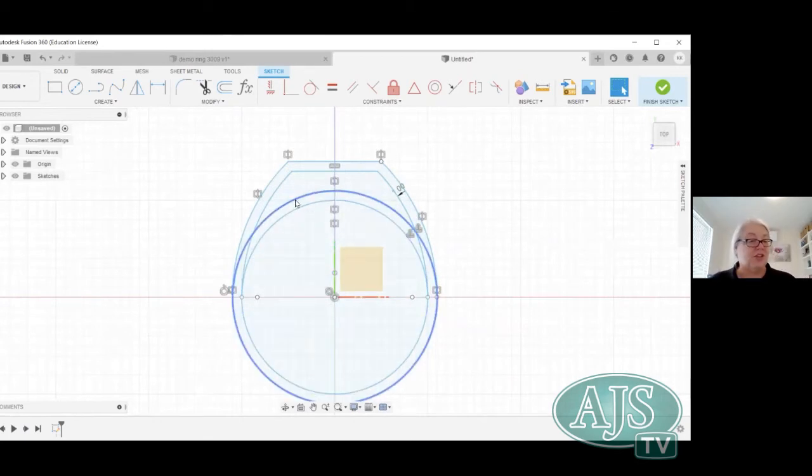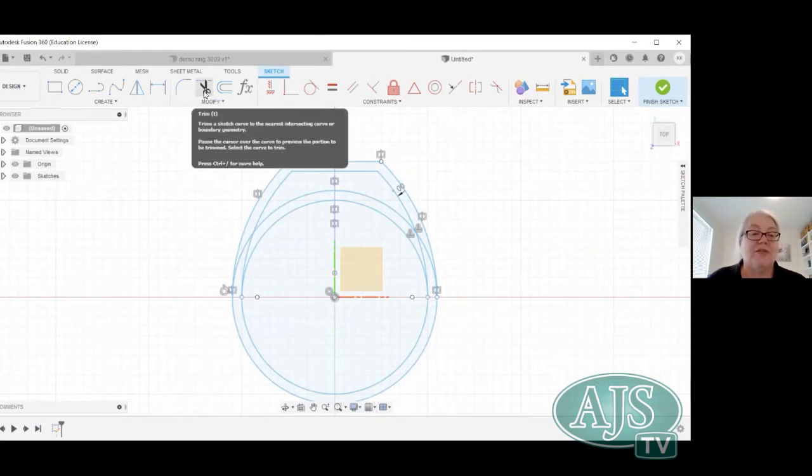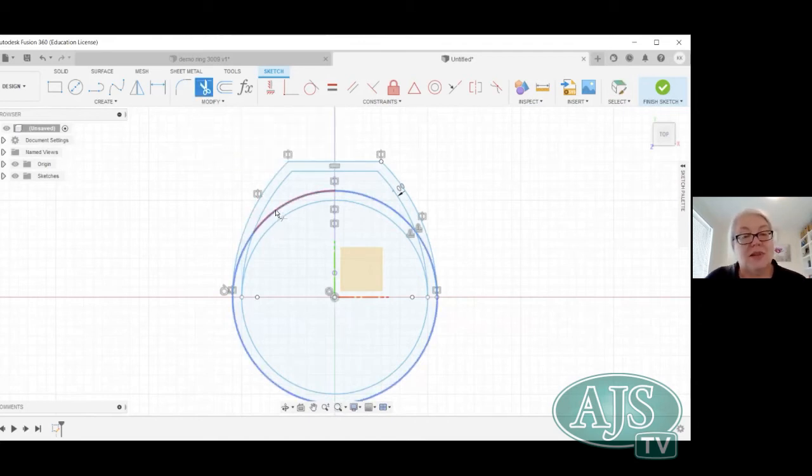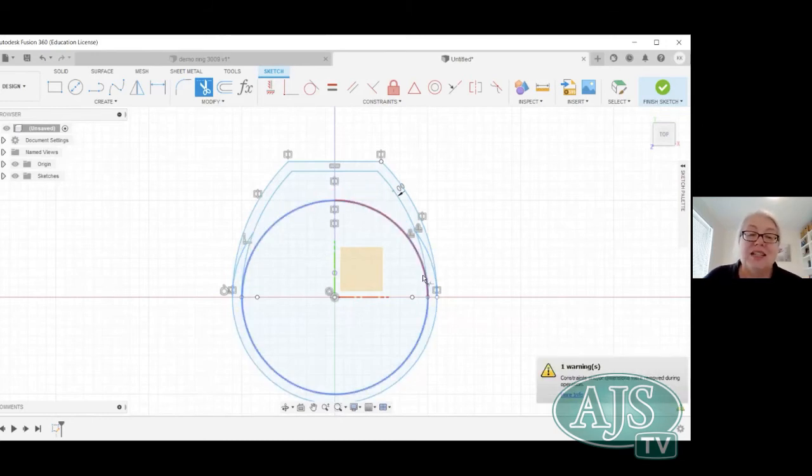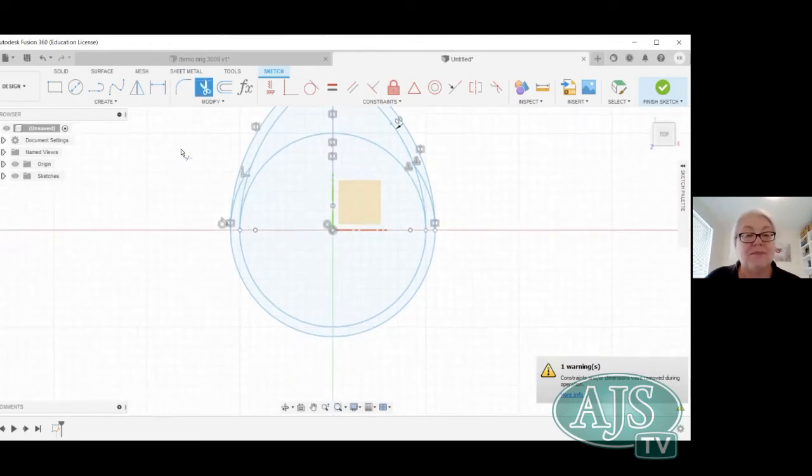So if I took a cross section through my signet ring, I wouldn't want like this layer of silver here and another layer of silver here with this hollow in between, simply because once we actually put that into the casting, it's going to be solid. So what we'll do is we'll just get rid of that little guy in through there when we do our rotation. So we don't have to get rid of it. You just need to be aware of the fact that it's there for when we actually rotate through. I might just cut this little bit out though, just to make life easier. We're not actually going to use this in our rotation, which I'm going to show you in a minute.